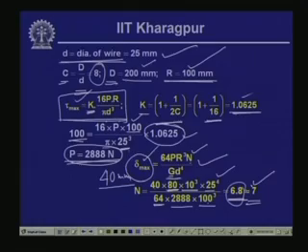So, the spring formed with a wire of diameter 25 millimeter can carry a load of 2888 Newton, and if we like to limit the displacement or the deflection of the spring to 40 millimeter, then the number of turns required is 7.